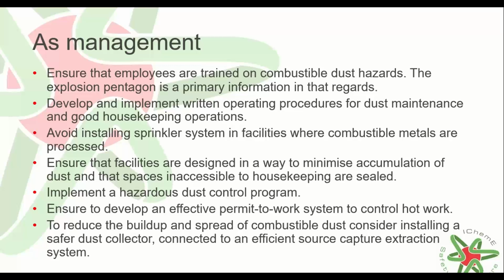And you can imagine that these recommendations are not only related to these two case studies, but they are also related to other cases in the past. So I collected these recommendations based on many other past incidents, and hopefully they are useful. And also, to reduce the buildup and spread of combustible dust, consider installing a safer dust collector connected to an efficient source capture extraction system. Extracting the dust in immediate proximity to where it is produced, source capture is an effective method of preventing dust from spreading. These are the examples. What can I do as a manager?